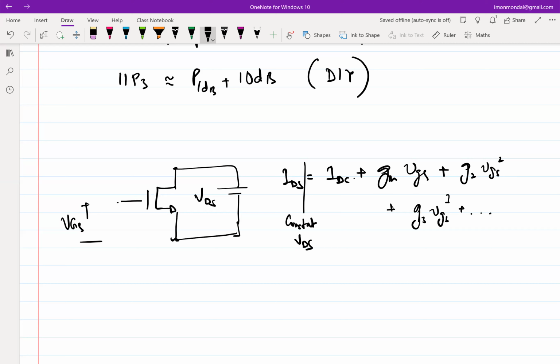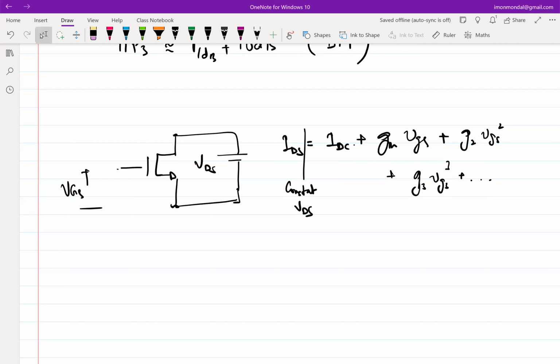If I make VGS small, it is going to lead to better distortion performance, no doubt. But if I do not want to make VGS small. When you say VGS small, which means what? Small with respect to something, right? With respect to what? At the edge of saturation.